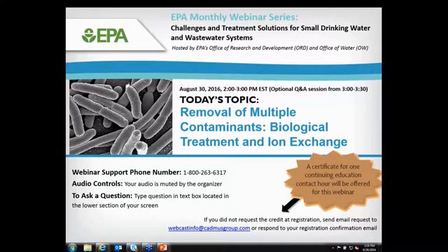Okay, thank you very much, Nick. We just have another question on whether or not ion exchange processes impact corrosion in the distribution system. Again, I think that's a little bit too long to answer on this webinar. We've done a couple corrosion talks in the past that are available on the ASDWA site. I think the short answer is with a resin like anion exchange resin, yes, you can change the corrosion indices of your water. So that would definitely be something you would want to look at if you had such a system.